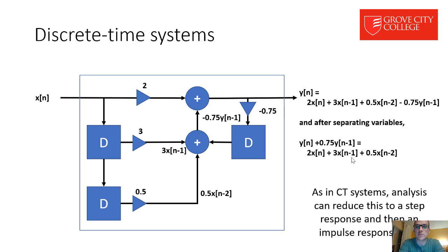So we talked about discrete time systems where you have an input x of n, you have an output y of n, and then your output is some combination of your inputs, delayed and scaled, and your previous outputs, also delayed and scaled. We talked about how different values on the scaling factors here can actually give you different frequency responses and different effects on the input signal, and that you would calculate the output by convolving the impulse response of this discrete time system with the input.